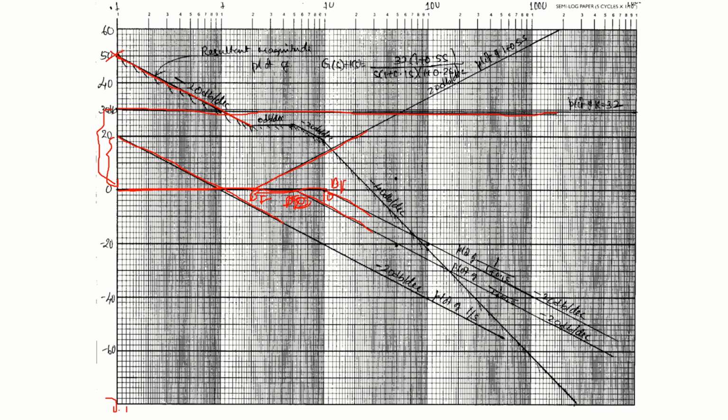Now from here this line is starting. The slope is plus 20 dB. This plus 20 and this minus 20 will become 0 till the next break frequency. From here this line is starting. The slope is minus 20. Add this minus 20 to 0, minus 20 dB per decade. Keep your scale on this. Draw till the next break.